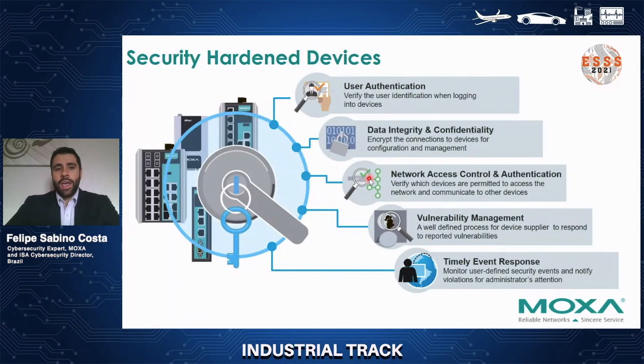Usually the first one is the hardening of the device. It's getting more popular, the certification of the 62443 for products. And in general, this is one of the first standards that goes deep into details on which kind of technology and or aspects, which in the standard they call fundamental requirements, the product should have in order to establish the minimal security level for that specific, let's say, risk, or to avoid that specific risk.